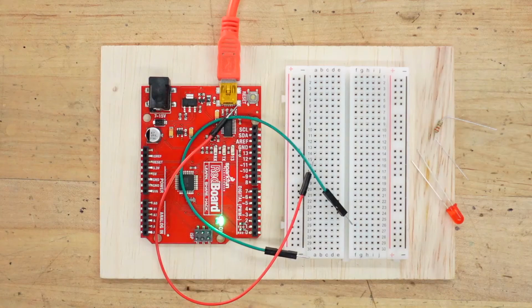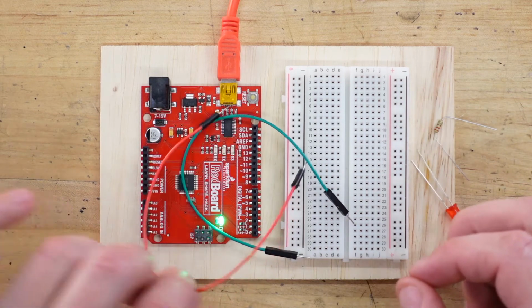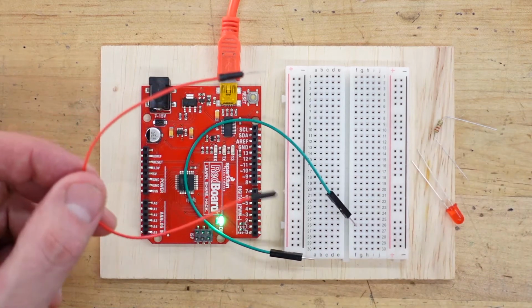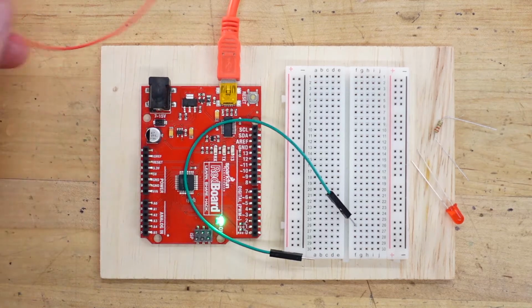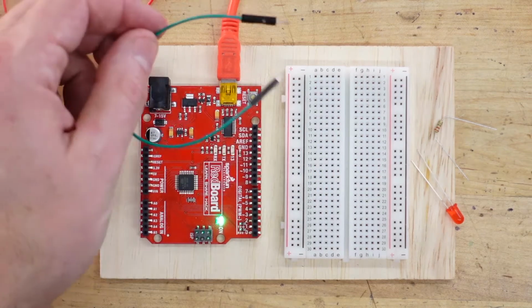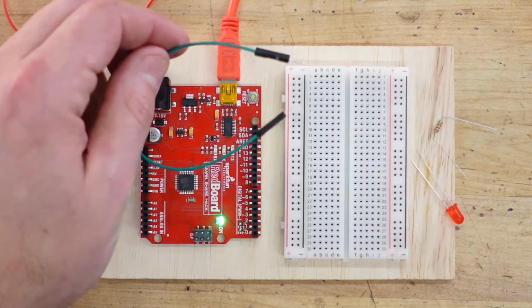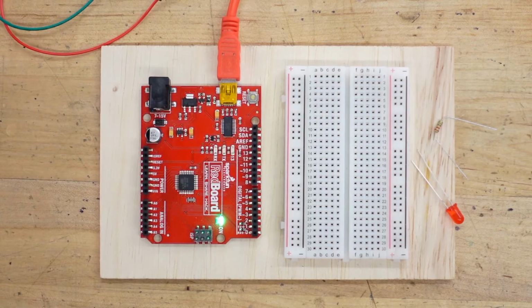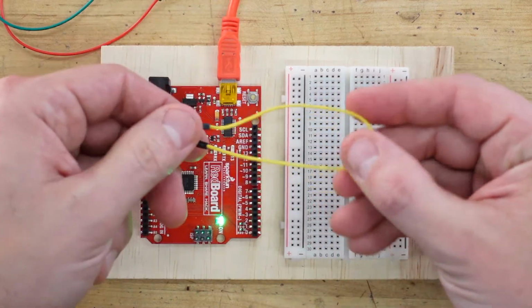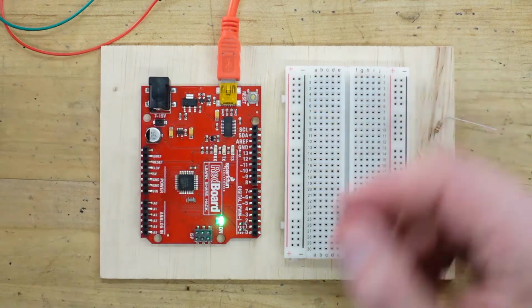And the reason is, I think it is much easier to keep things sorted if, by whatever rubric you determine, you stick with certain colors to express certain things. For me, I'm pretty much always using a red wire for my positive voltage, a green or maybe black wire for my ground, and a yellow wire for signal. So I've got these laying out here.